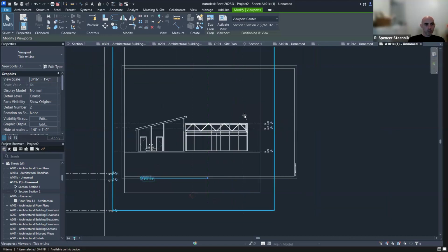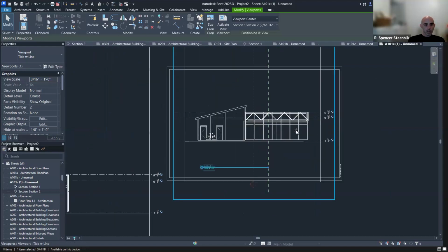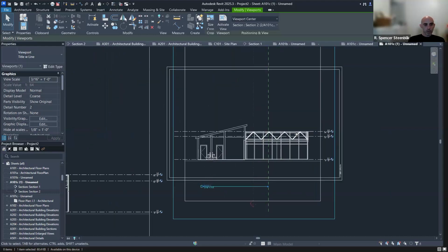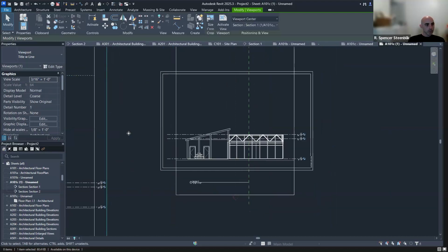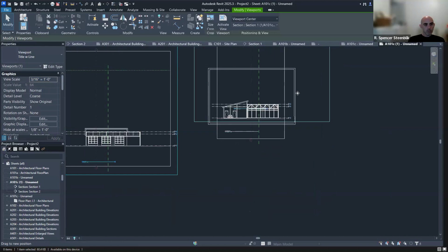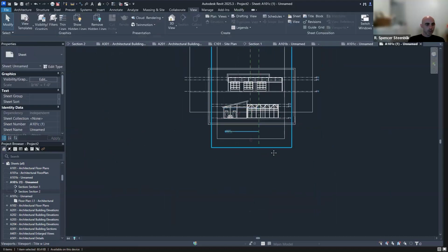That fits better on the page. You'll want to be consistent about the sizing that you use. You might even be able to fit 2 views on the page if you do them the same. Going down to 3/16, yeah, that would work. You could fit both on the page there. You'll want to adjust that, but yeah.